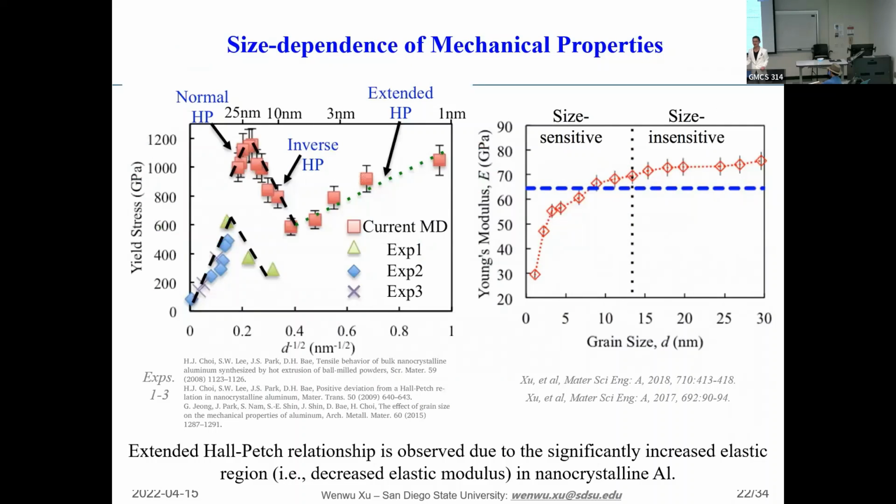And then we would also like to compute the mechanical properties and compare with the literature data, just to verify our estimation results. We also computed the yield strengths of each one of those models, from larger grain size to smaller grain size. And we see a relatively good correlation between the yield stress value coming from the literature or from the experiments and our simulation results.